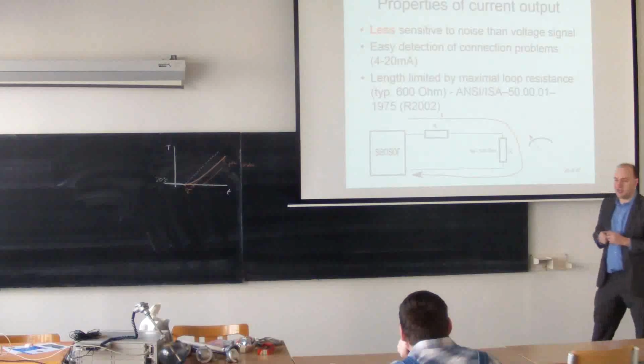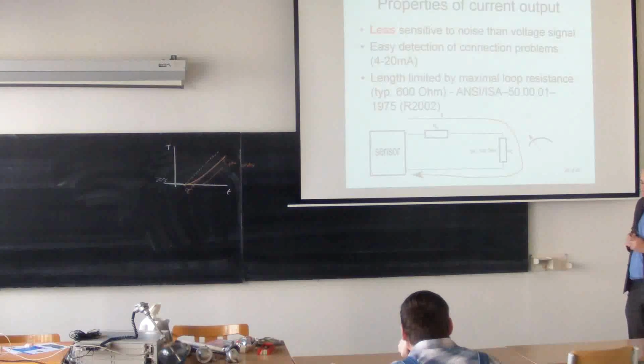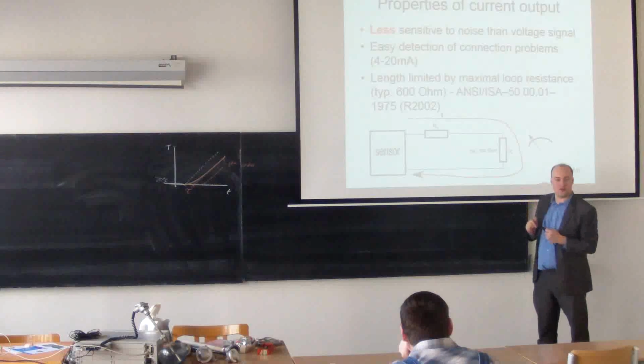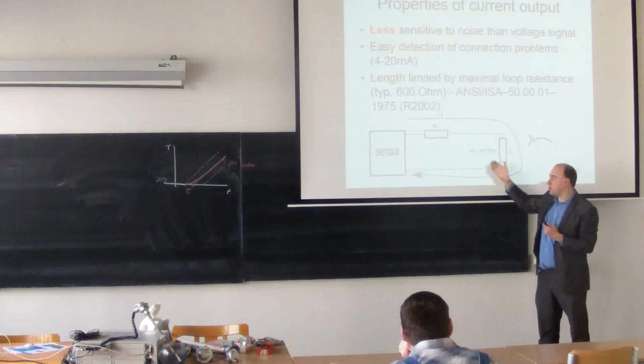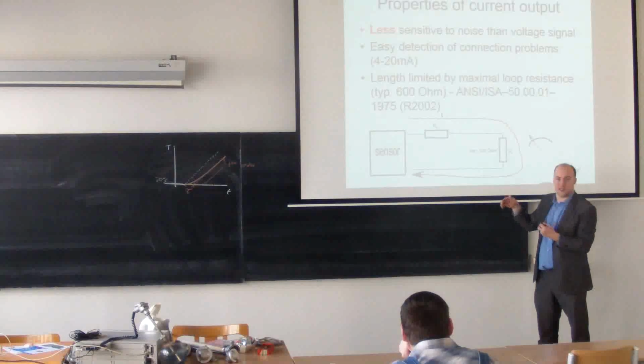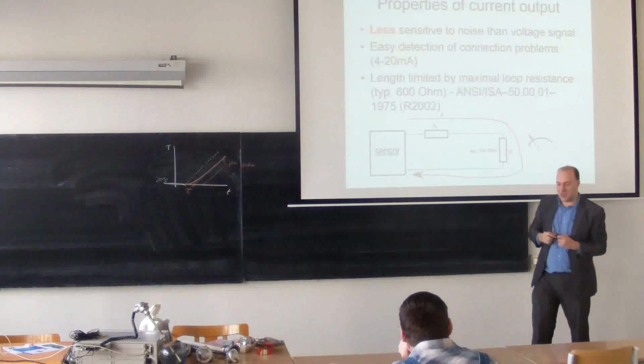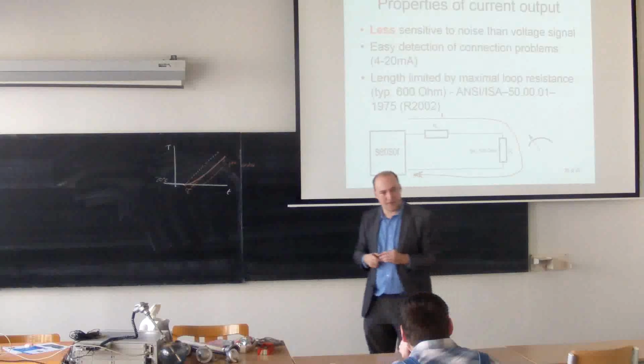The second advantage is that the current output has a higher immunity against noise. So it means that if some voltage is induced into those two wires, the current will still stay the same, unless it's very high energy. So current output has higher immunity against noise.